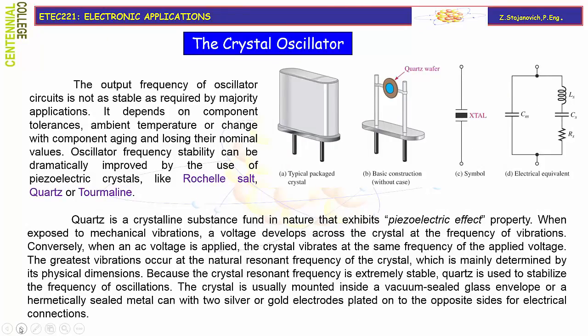We will say a couple of words about the crystal oscillators. The output frequency of oscillator circuits is not as stable as required by majority of applications. It depends on component tolerances, ambient temperature, or changes with component aging or losing their nominal values. Oscillator frequency stability can be dramatically improved by the use of piezo or piezoelectric crystals like Rochelle salt, quartz, or tourmaline.